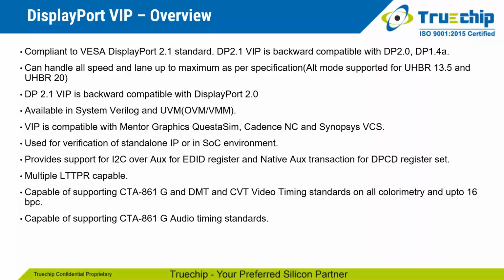Multiple LTTPRs, capable of supporting CTA 861G, DMT, and CVT video timing standards on all colorimetry and up to 16 BPC. Capable of supporting CTA 861G audio timing standards.